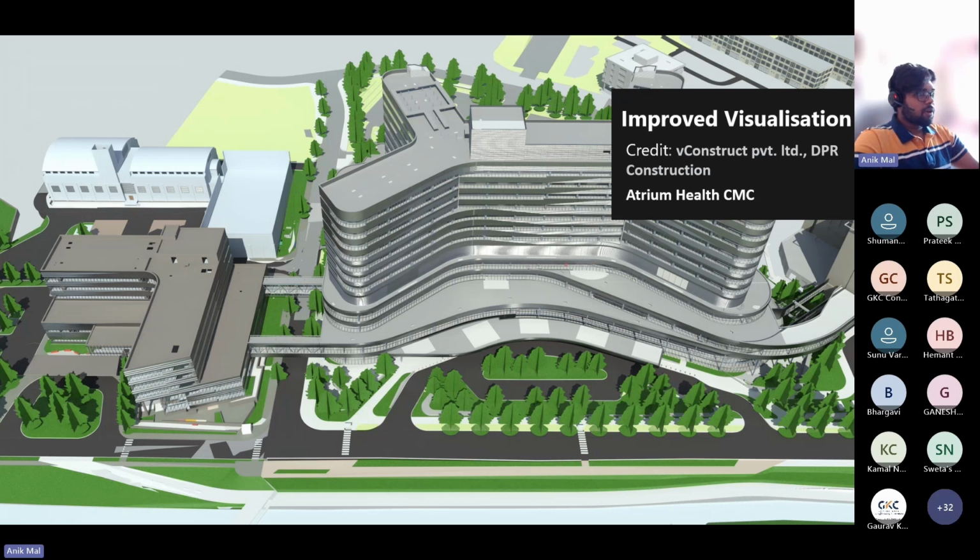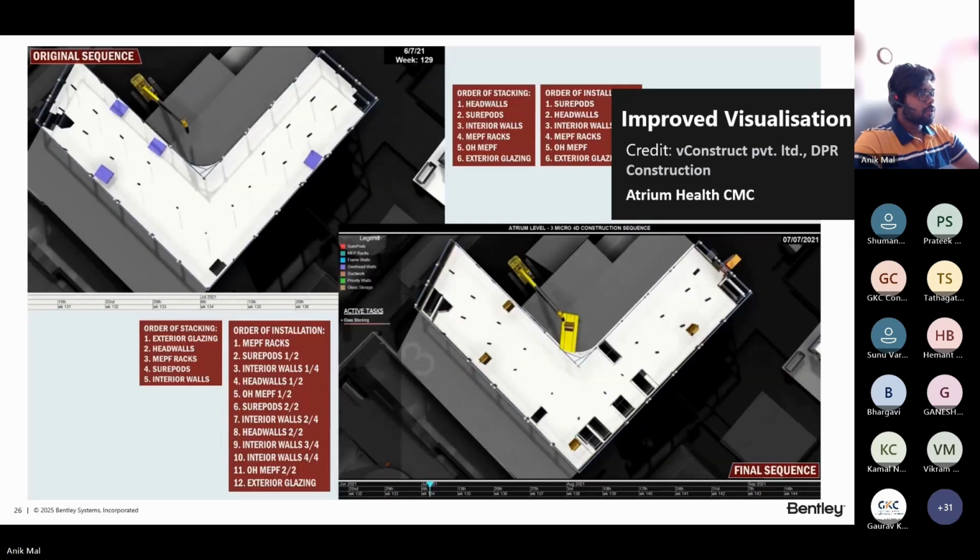The project is delivered by implementing various lean concepts both during design and construction. Over 60% of the project was prefabricated in an offsite warehouse, improving the schedule, quality and safety. The team had an initial P6 plan, which was further refined in Synchro 4D Pro. This refinement or optimization was only possible due to better visualization of the schedule.